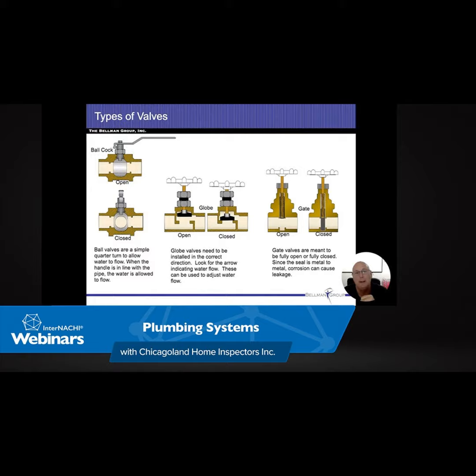All right. Now, you can replace these anode rods. The manufacturers recommend that you replace the temperature pressure relief valve and the anode rod every 5 years, and that you flush the system. Don't drain it. You just want to get that water flow out of the drain valve at the bottom. You flush the system once a year until clean water comes out of there, and that way you get rid of all the debris. But yeah, those anode rods get eaten up, the pressure relief valves get eaten up.